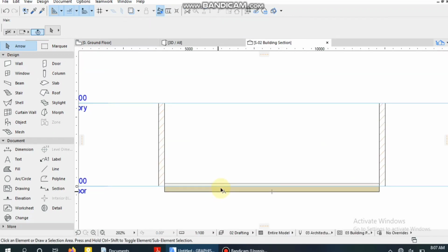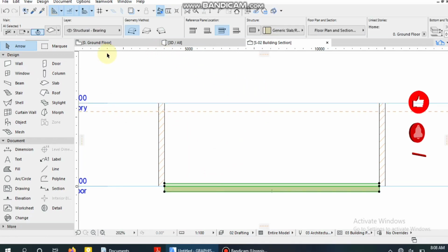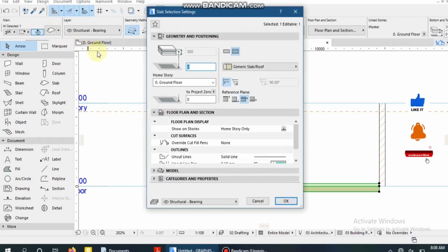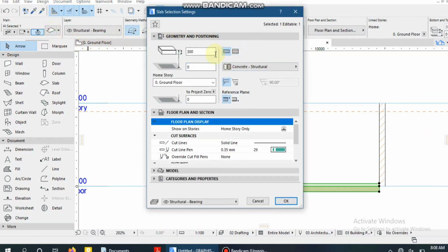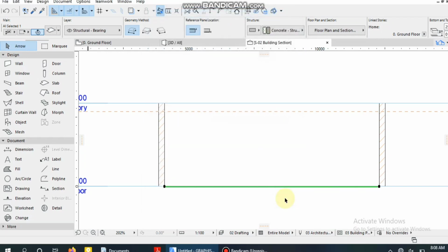So now we're going to have to mark that the ceiling starts with an offset of 300 mm, or it drops down by 300 mm. So that's what we're going to do. We're going to type here 300, right? And we're going to set this slab. Let us use a thickness of 25 mm, just because. Thickness of 25, right? And let's change the color to white.